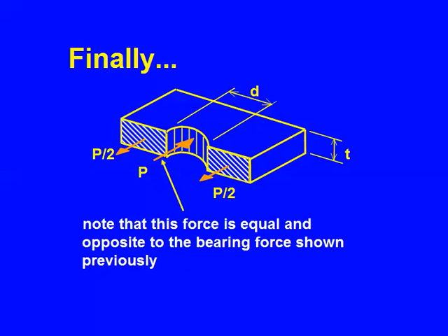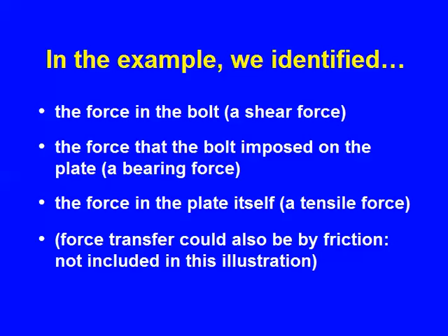So we identified the force in the bolt, shear force. We identified the force that the bolt imposed on the plate, that's a bearing force. And the force in the plate itself, in my illustration, it's a tension member, and that's a tension force. Not our problem this afternoon, but it's your problem as a designer.